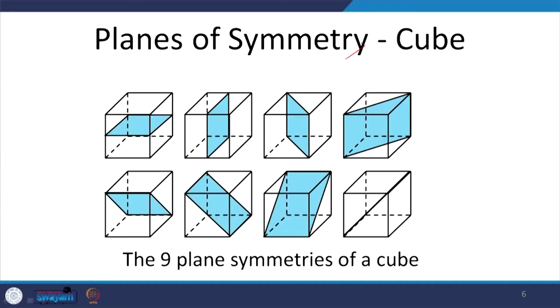So, if the plane is parallel to the base, how the cube is going to be placed, in that case we will see a square. If it is perpendicular, then also we will see a square. If the plane is inclined but perpendicular to the base, we will be seeing rectangles, because this will be the length of a diagonal and the height of the cube. In case of parallel and perpendicular, we will get squares.